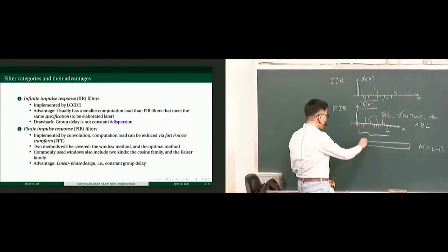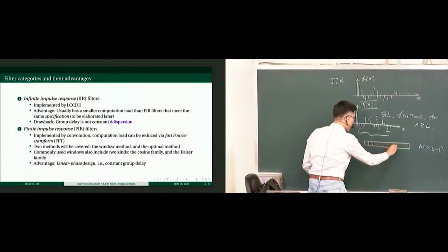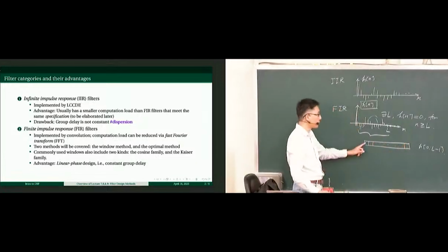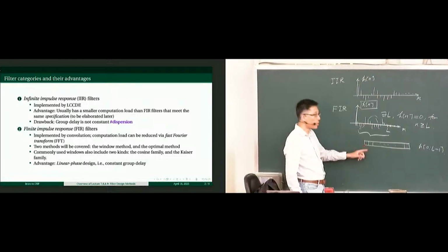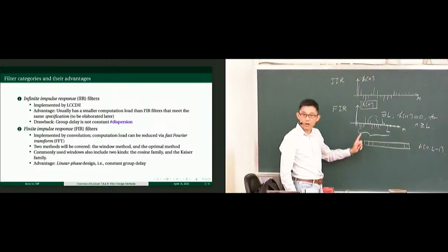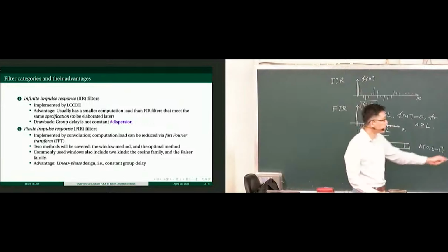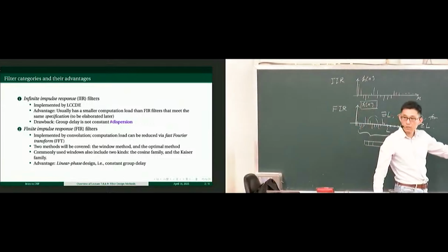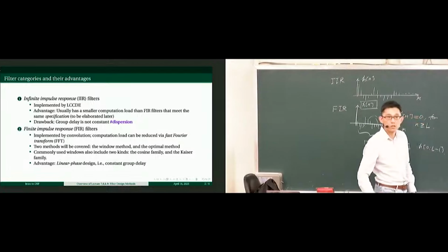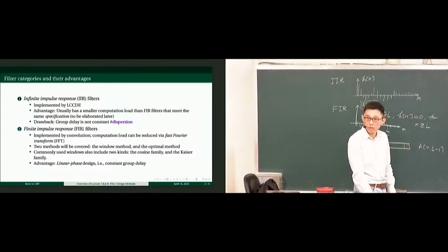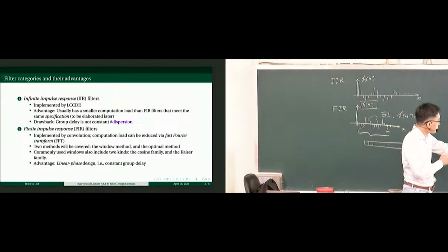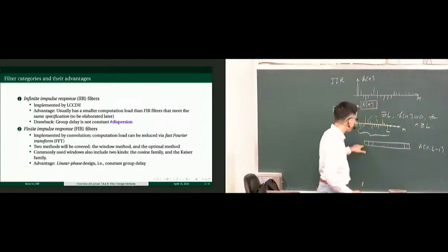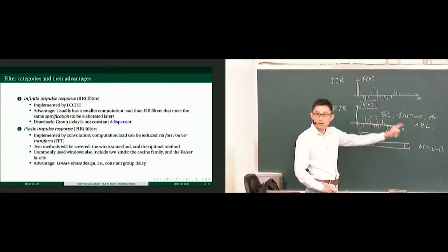Literally, what you would do is store your filter samples in one array, and then convolve this array with your signal. So an FIR filter is implemented through convolution. That clear? Because filtering is convolution in time and multiplication in the frequency domain. So FIR filters are always implemented by storing all the sample values and then convolving.